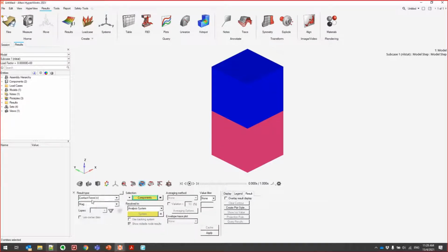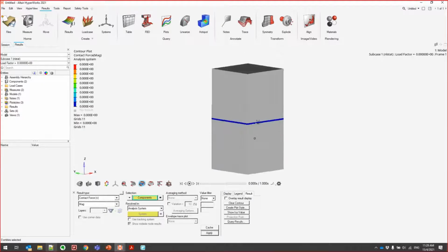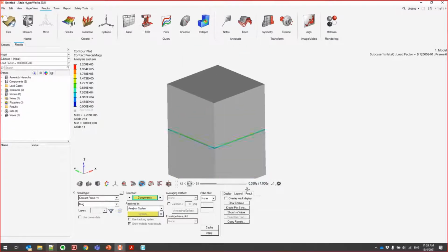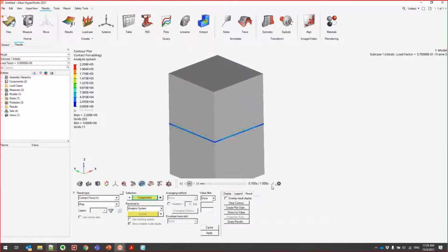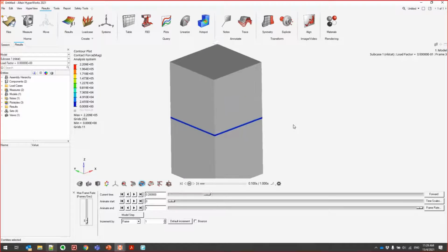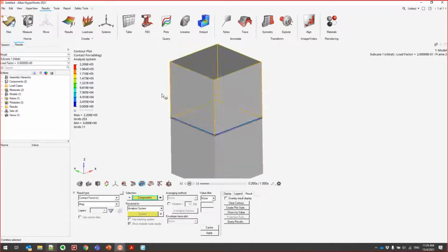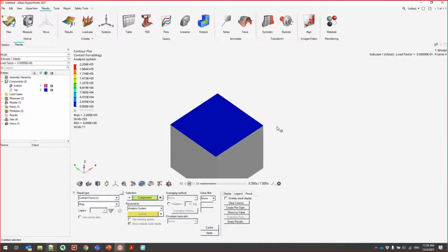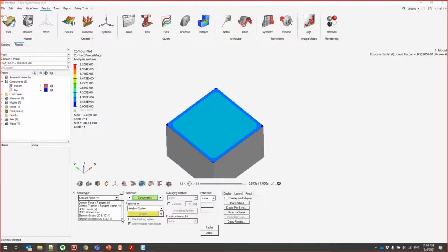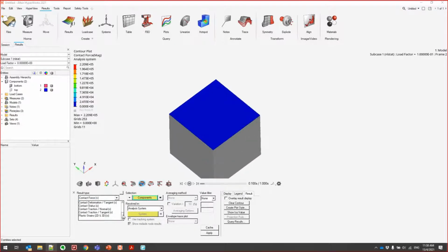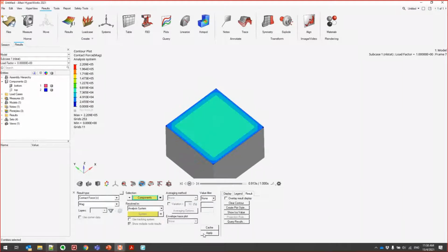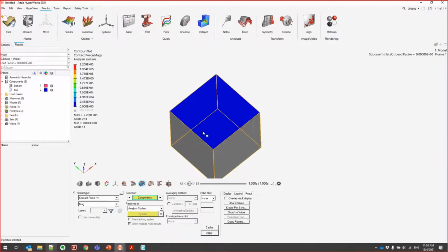Okay, so we can always look at contact force when we are looking at forces at contacts. So this will give us a better idea on whether we generate the contact or not. Too fast. Okay, so let's remove one of the blocks. See, contact established. You can also look at contact pressure to see contact force. Yeah, contact force. Right. So you can see the pressure distribution.